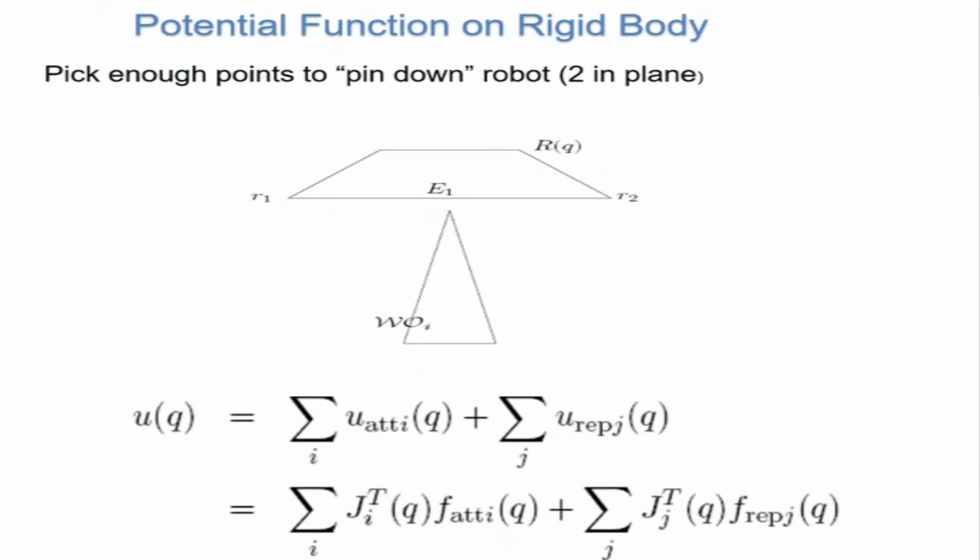What we apply this for is by choosing different points on the robot and seeing what forces are acting on those points. Say, for example, you have a very large robot like this and a sharp obstacle. Suppose I take the force acting here at point P1 and the force acting there at P2. Then I can convert these forces at P1 and P2 into a moment which is acting on the robot and move it accordingly in C space.